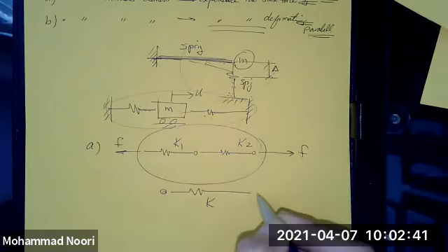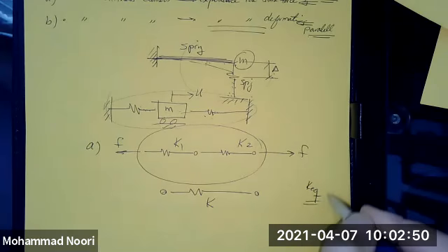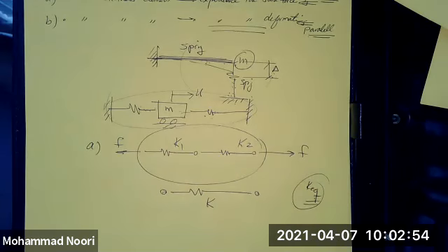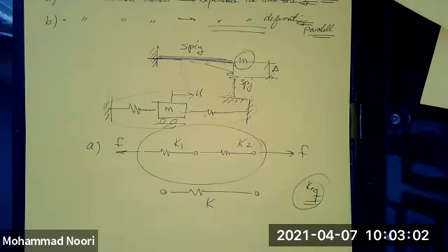It is always the case that we want to combine all the stiffness elements in a structure so that we find that equivalent spring. We did that already for some simple problems by just setting up the equation of motion. But in many cases, it's not easy to do it that way. So we use our understanding of how these springs are oriented.